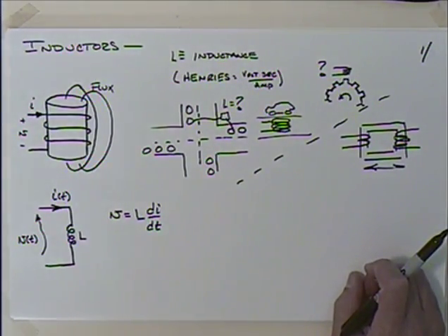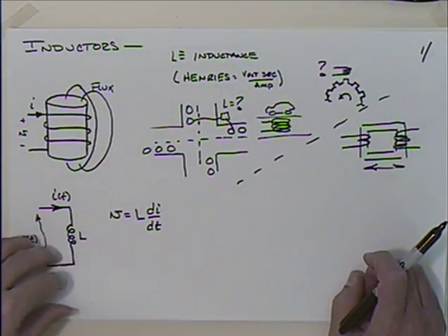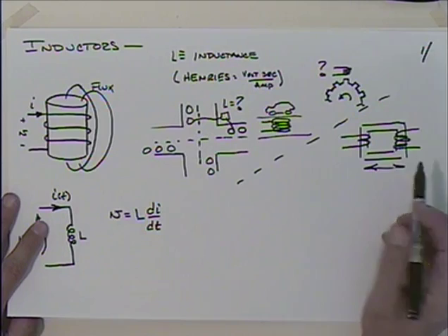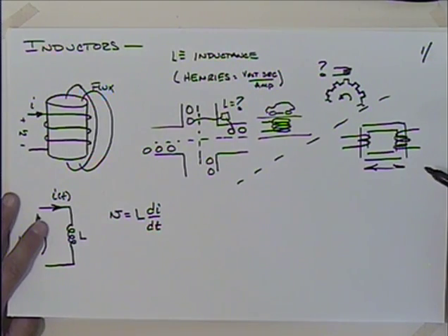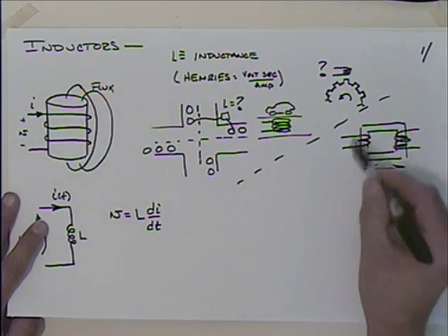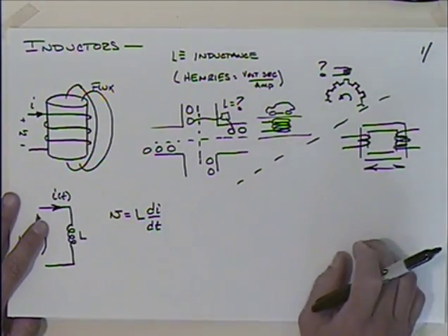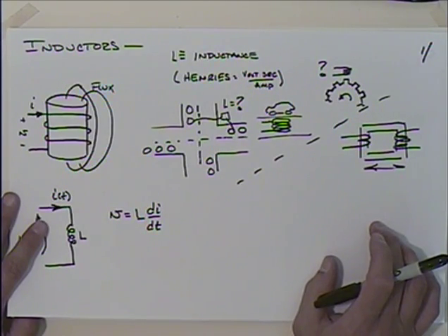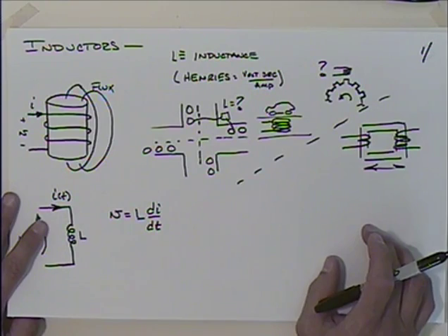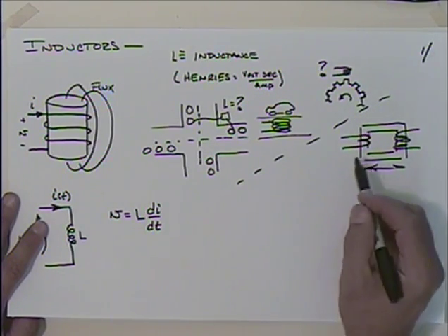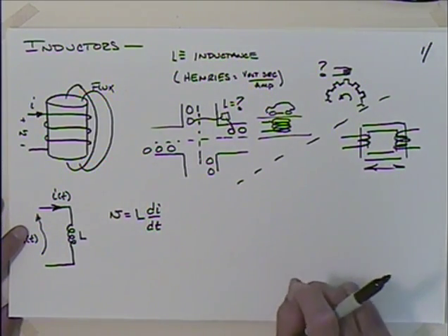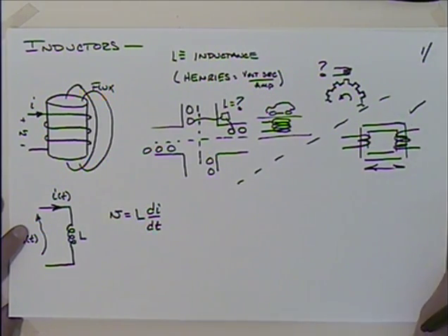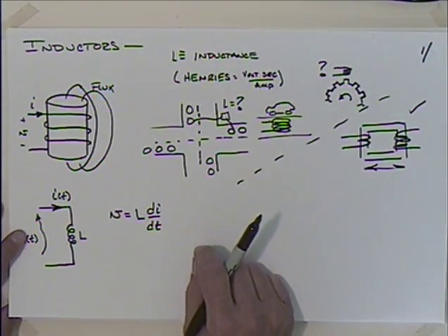If you want to step the voltage up, you can use it one way. If you want to step the voltage down, you can use it the other way. There's a corresponding increase or decrease in the current, so you're not changing the power. You're just stepping voltage up and current down, or vice versa. And we actually use this in the automotive system. This transformer is what you have with a coil when you want very large voltages in an ignition. You're going to need 40, 50,000 volts to fire that spark plug. You'd have something like this, and the points would just be opening and closing it, so you wouldn't have a constant current. So we'll talk about a lot of this on its own next term, but there's a lot of use for inductors.